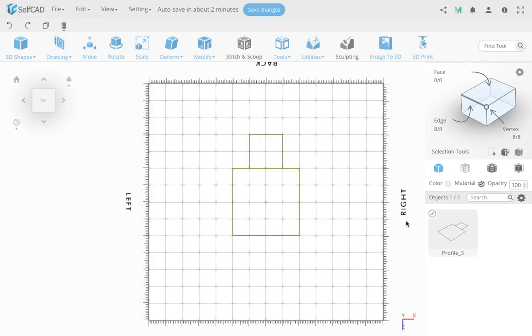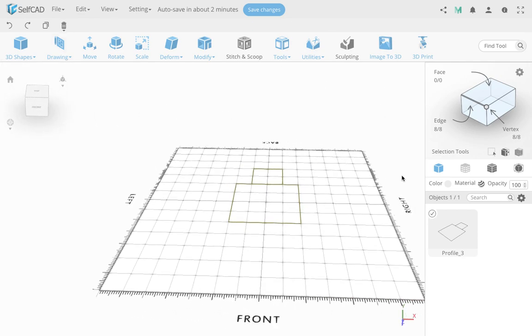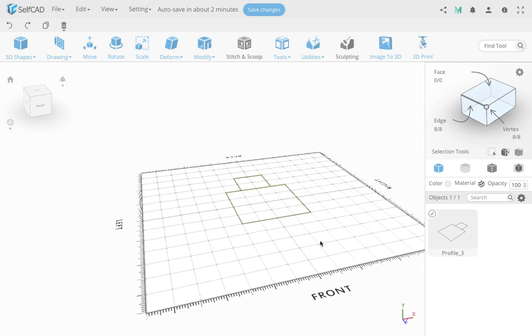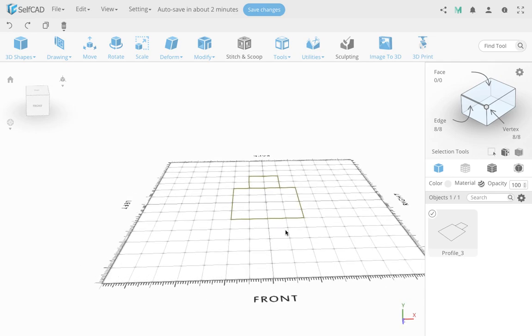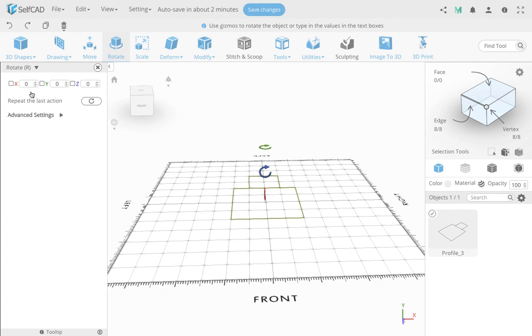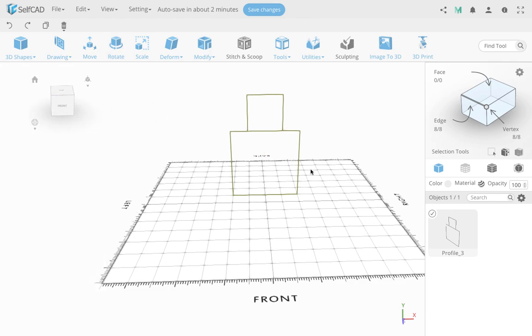So I'm going to finalize, but before doing it, the Revolve will rotate around, which in this case will be my z-axis, which means it will actually go underneath the grid. We'll have to push it up, and I wouldn't be able to visualize what I want. I want to visualize this in the height. So in order to get what I'm looking to get, I'll rotate this by -90. So I'm getting it standing up. And this is actually the shape that I intend to get. I'll just tell you that's not what I'm going to get first, but that will be a good example to explain. And then I'll show how you can actually get this using the Revolve.